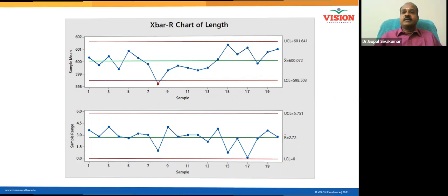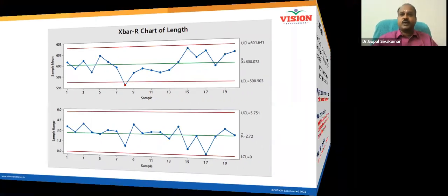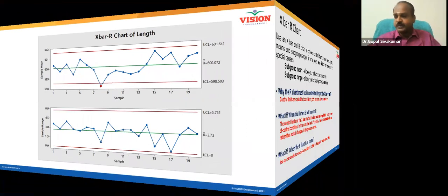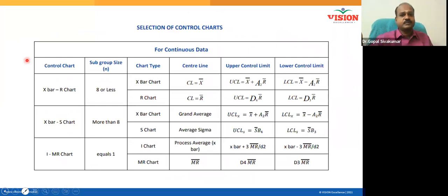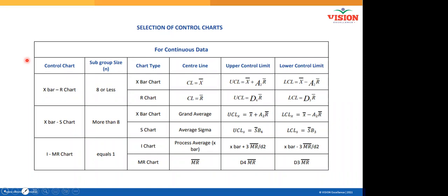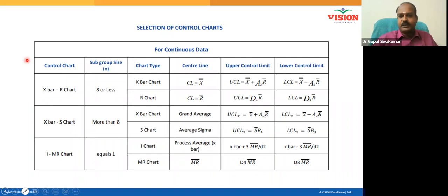Yes. So now you are a master of dealing with the control chart. And this is the formula, right? I don't want any of you to mug up the formula. Rather, know that a formula exists. You can always refer to it, always read it, always do it manually once. Unless and until you ink your hand, you can't learn. I strongly suggest, I have already shared this, right? An Excel file. I share the data and expect each one of you to plot an R chart, plot an X bar chart yourself in a graph sheet. And then you will see that all your doubts are clarified, right? And look at the formula and everything.